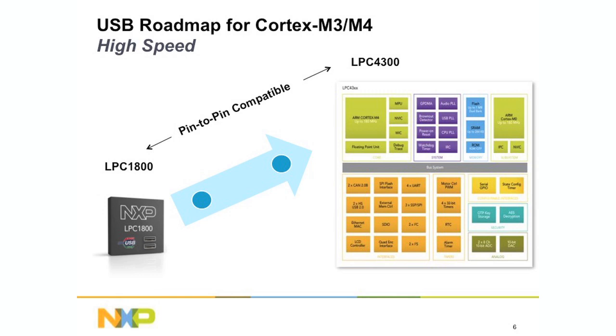If you look at the peripheral set, you will see 2 CAN interfaces, 2 high-speed dual-host controllers. That's something very unique about these solutions. We have not just device, or not just host, but we also have dual-host solutions with our portfolio. Followed by the typical suspects, the SSPs, the I2S, and the I2C interfaces.